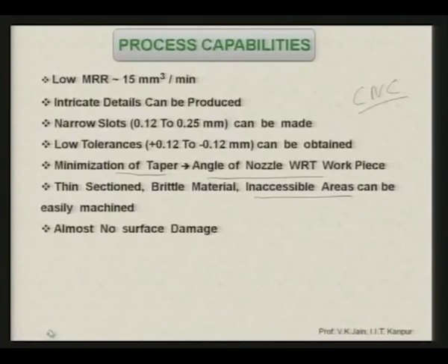There is almost no surface damage, because there is not a large amount of heat generation and the workpiece is always in contact with the air. So, the rise in the temperature is comparatively very low, and there is no thermal damage to the workpiece, and large forces are also not acting. So, there is no mechanical deformation of the workpiece.